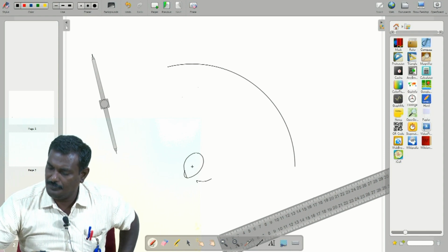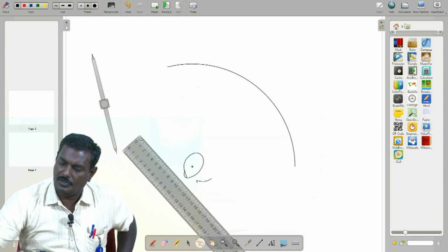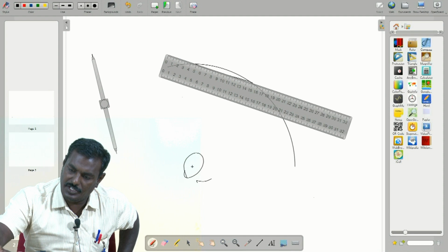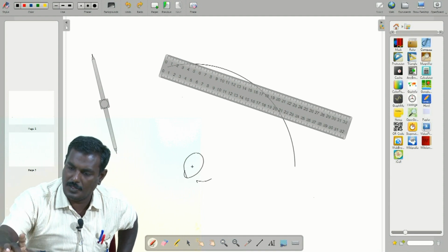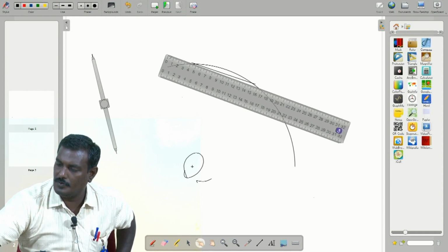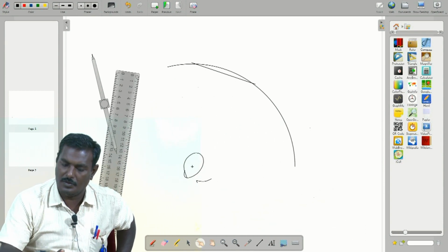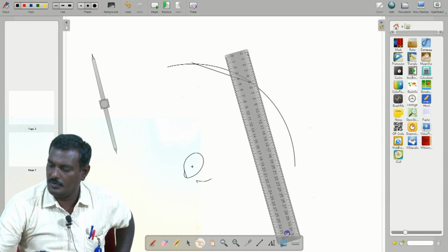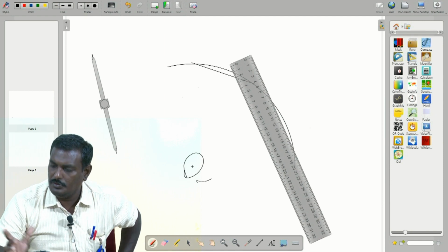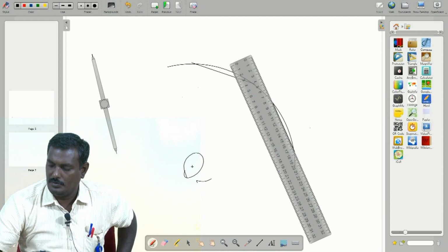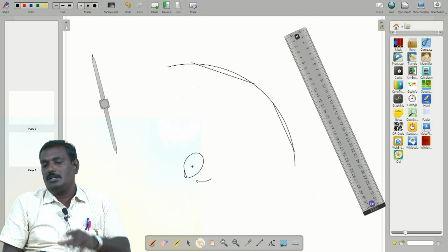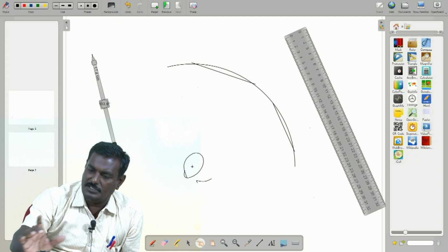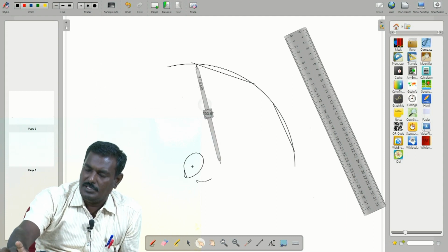For such a case you have to draw two straight edges, two chords, in the arc. For this you have to find the bisection line using a compass. Using this compass, from this point you have to draw an arc.